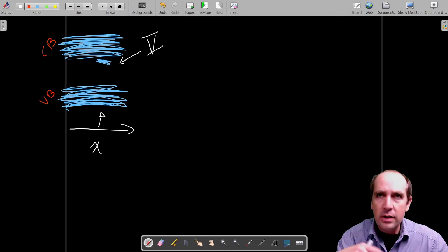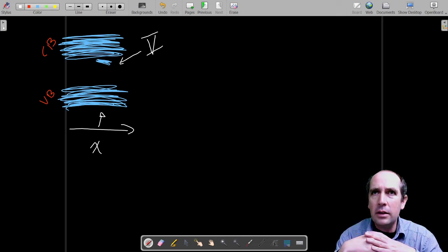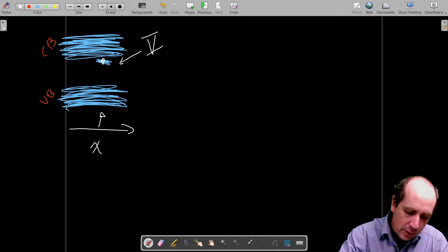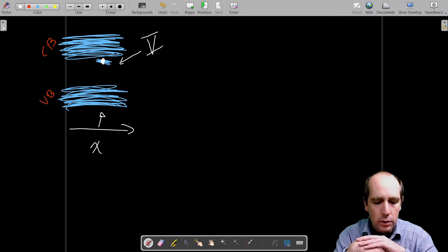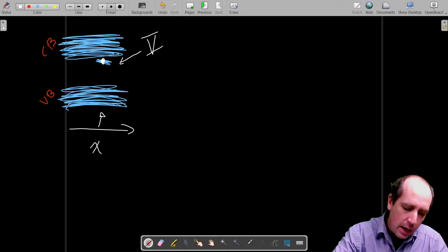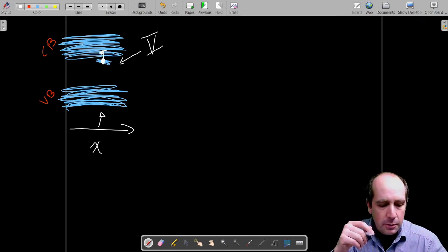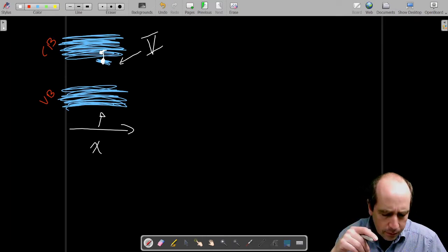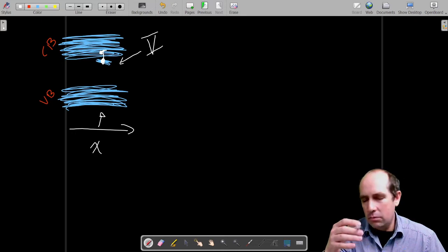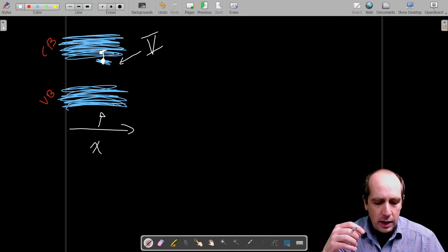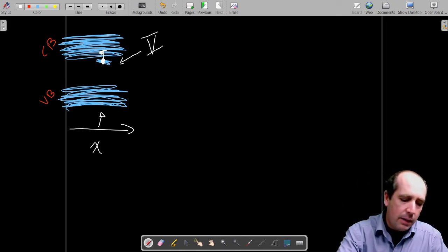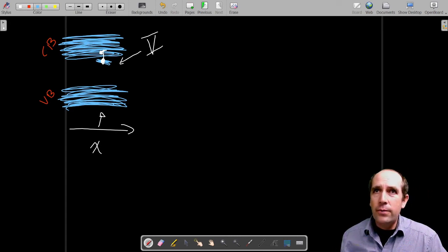Now, this level is usually so close to the conduction band that simple thermal excitation, a few milli-electron volts or a few tens of milli-electron volts, will be enough to promote the electron that lies here and that was weakly bound to the group 5 material into the conduction band. So this process of promoting happens naturally at room temperature. So in that sense, at least at room temperature, we really are providing electrons that are injected or promoted into the conduction band just naturally. The same happens for group 4 electrons.